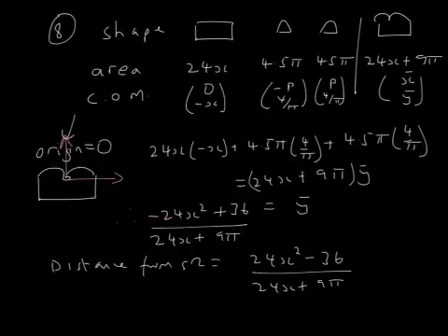So that's changed sign. In case you're not sure, I took the y direction to be upwards. As I say, maybe that wasn't the best decision, but that's what I did. We want the distance of the centre of mass from this line here that I'm drawing, so it's going to be downwards. So the distance is going to be in the opposite direction to this. That's why I've changed the signs.